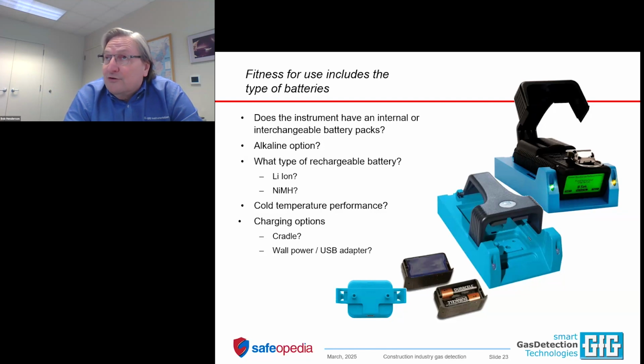A lot of corporations, a lot of professions, like if you're an industrial hygienist, your code of conduct requires you to calibrate the instrument before using it and to calibrate it after use to ensure that you have not lost any capability of or accuracy in the interim. So there's nothing wrong with calibrating the instrument more frequently, but those are the minimums that are set up by OSHA.